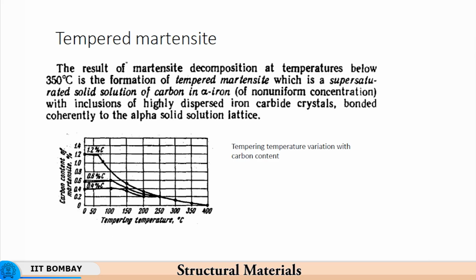The carbon coming out reacts with iron and creates cementite, meaning Fe3C, iron carbide, and that iron carbide is another hard phase. So, you have tempered the martensite, you have got back the lost fracture toughness, and you also have gained in terms of formation of iron carbide and alpha iron, providing a relatively good amount of toughness.